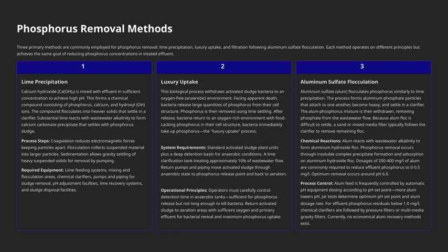Finally, let's discuss aluminum sulfate, or alum, flocculation. Alum reacts with alkalinity in the wastewater to produce aluminum hydroxide floc. These aluminum phosphate particles attach to each other, becoming heavy enough to settle in a clarifier. The removal process involves forming insoluble complexes that trap phosphorus. Because alum floc can be slow to settle, a filter, like a sand or mixed media filter, is often employed afterward to catch remaining floc particles.